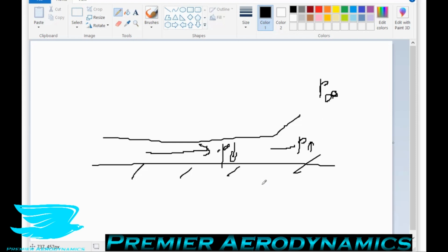So underexpanded means that the flow is exactly that, it's underexpanded. It hasn't expanded to the point where the pressure equals the free stream pressure. It's actually lower still. You then have perfectly expanded, which means that it is the same as the free stream pressure. Then you have overexpanded, which means that the area is being expanded too much, and now it's at a higher pressure. In turbojets, it's actually the opposite, because turbojets have higher pressure inside the turbine, and then you have to reduce the pressure to match free stream pressures.